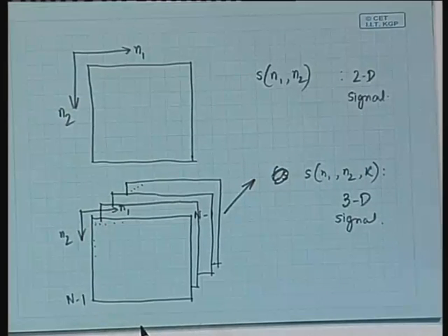So, what it leads to is that the fundamental bit rate one obtains in the case of image and video is going to be much higher as compared to that of the speech signal. Because after all, why was the speech signal fundamentally not very challenging from an encoding point of view? You take a 10 kilohertz sampling rate, because your signal was restricted to at most 3.4 or 4 kilohertz for speech, have 8 bits per sample, and you are going to have a bit rate of 64 kilobits per second.